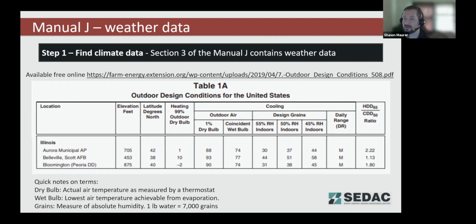The reason that's important is when you go beyond Manual J to the Manual S to sizing your equipment, as you're going through your manufacturer's data, it has an impact on what the actual output capacity of your system is, depending on what those returning relative humidity to the unit is. The other conditions are for if you have specific situations happening.